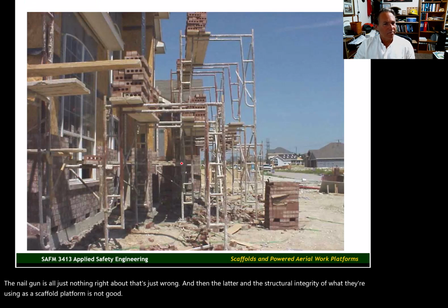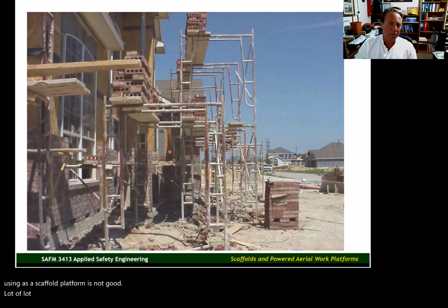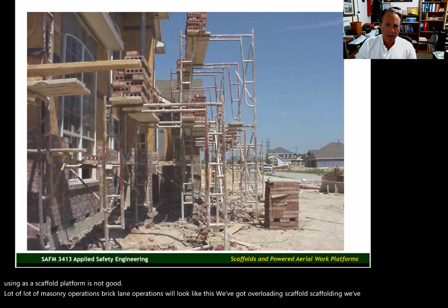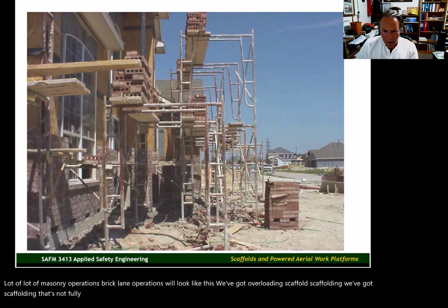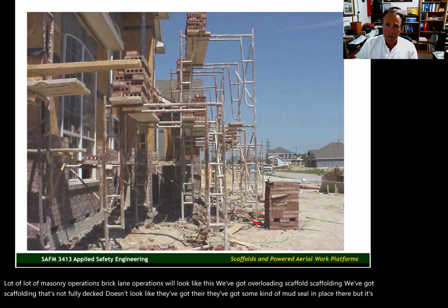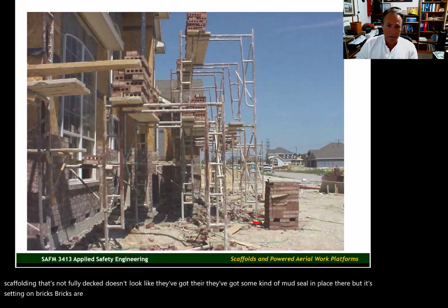A lot of masonry operations, bricklaying operations will look like this. We've got overloaded scaffolding. We've got scaffolding that's not fully decked. Doesn't look like they've got some kind of mud seal in place there, but it's sitting on bricks. Bricks are not designed to carry any kind of loading.